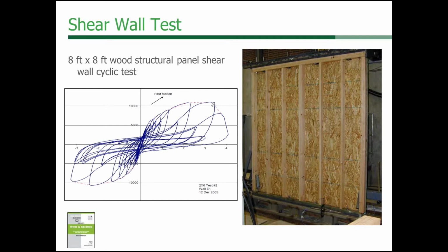Now the other thing to view from this graph is that after we've exceeded this displacement and applied more strength, you can see that there was a failure. So it can't resist any more load, and there was a failure here, and it goes beyond the 3 inches, but it's still holding in place.